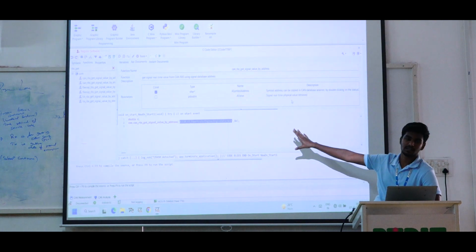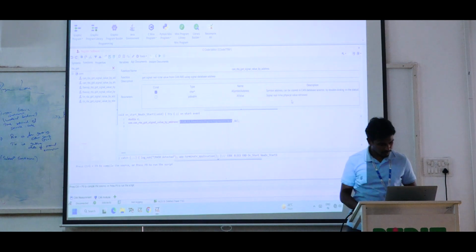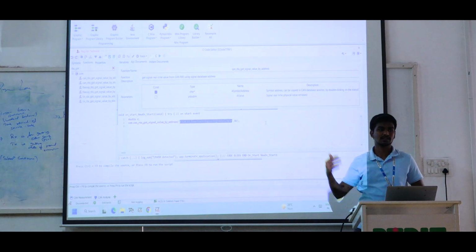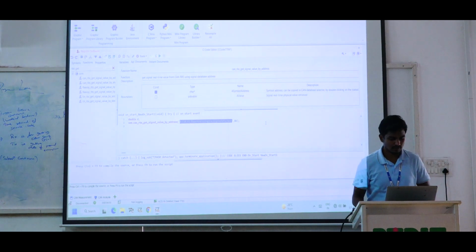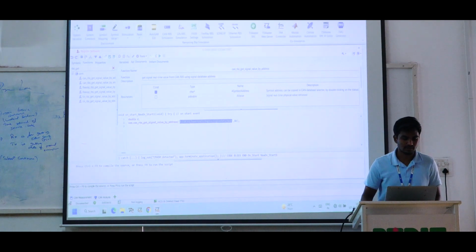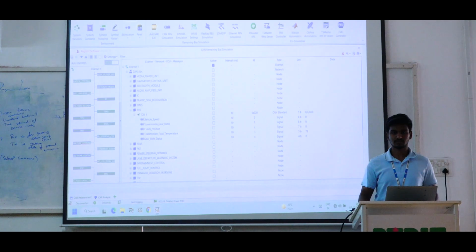So we need this database address. We are going to use get signal, which means we are going to get the signal value of vehicle speed. So we need the vehicle speed address. For that I am going to the RBS simulation. Go to RBS, open the TCU, and then open the TCU message. The vehicle speed signal is there now.